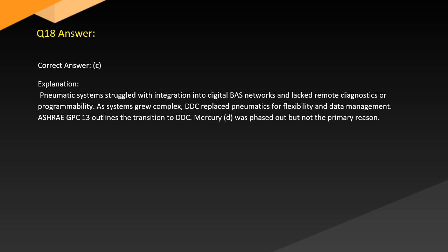Answer. Correct answer: C. Explanation. Pneumatic systems struggled with integration into digital bus networks and lacked remote diagnostics or programmability. As systems grew, DDC replaced pneumatics for flexibility and data management. ASHRAE GPC 13 outlines the transition. Mercury, D, was phased out but not the primary reason.